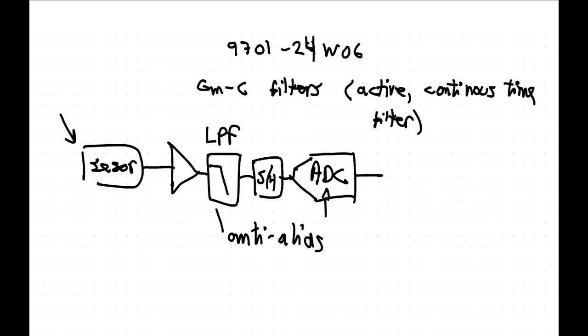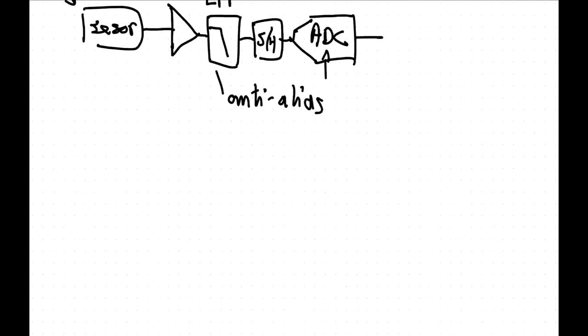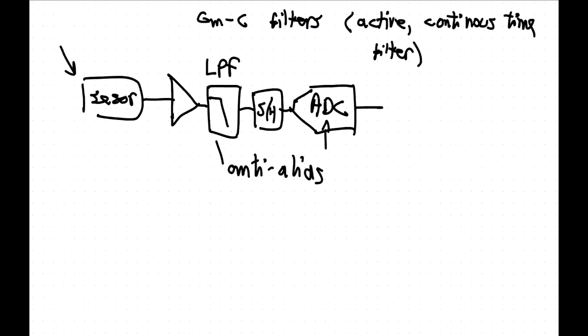Or else you can just make sure you use a signal chain that's inherently anti-aliasing. It's just about limiting bandwidth. Well, usually when we sample, we don't have high powers at high frequencies, so probably there is aliasing, but it's so small. It depends. Anyway. Okay. So, anti-aliasing filters.